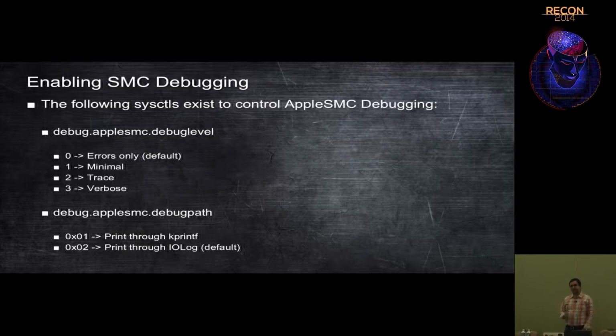But the SMC actually does have an event log on its own that I discovered a few weeks ago. I'm still trying to dump it, but the SMC has an internal RAM of the last 10 keys that were sent to it as well. So there should be a way to determine that as well, but I'm still not sure how to do that. I'll update the tool once I can figure that out.